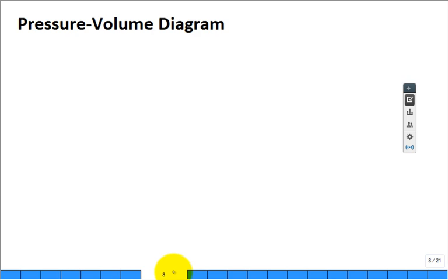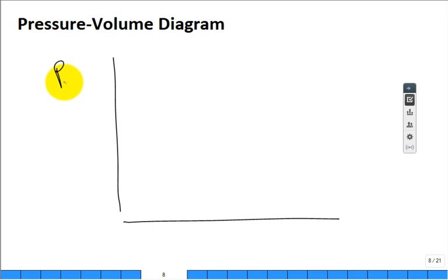Well, let's talk about a pressure volume diagram. Pressure on the y-axis, volume on the x-axis for a true four-stroke gasoline, spark ignition internal combustion engine. What we want to do is put a line right here, and that's atmospheric pressure, because sometimes the pressure inside that cylinder is below atmospheric pressure. That's how you draw in the air across the air filter and through the valve intake structure.